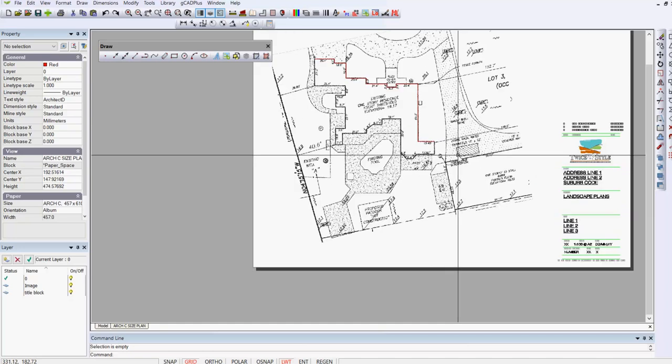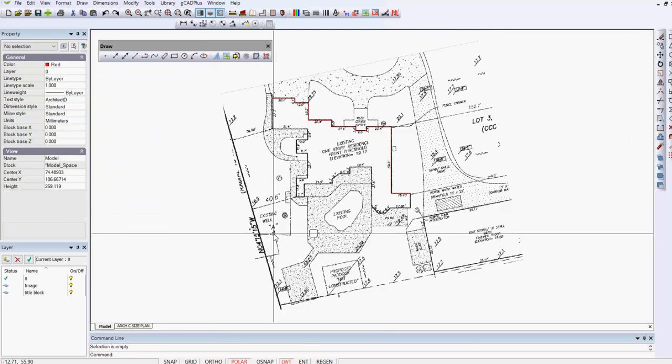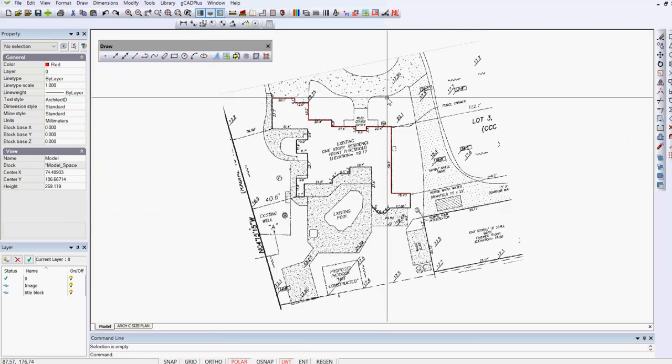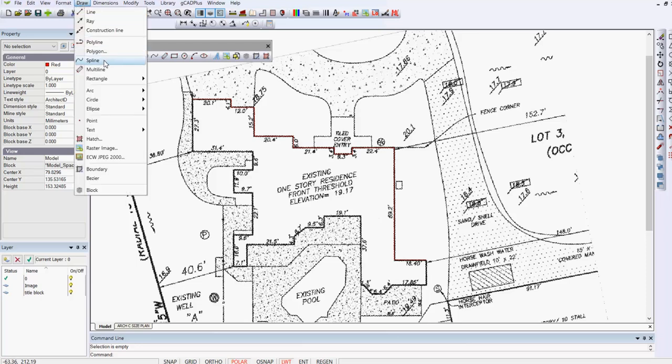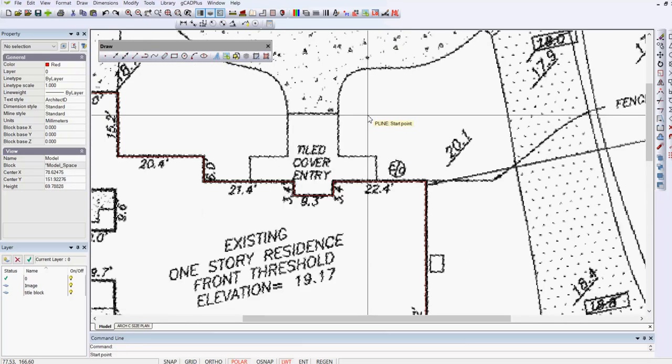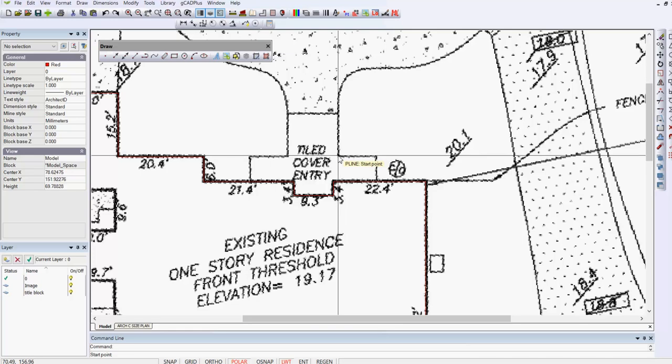so that as we create more and more of our landscape design over the top of the existing detailed information. So for the sake of argument, if we want to put these curving pieces in, of course we would use the Polyline command and quite possibly apply some sort of curve fit.